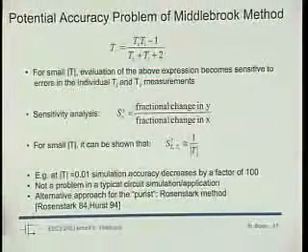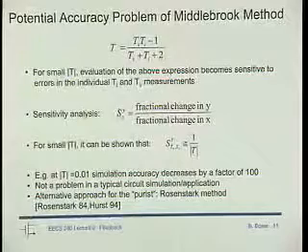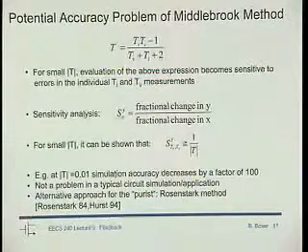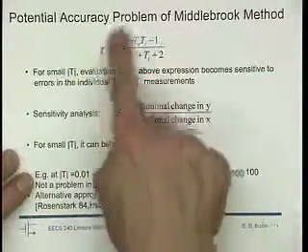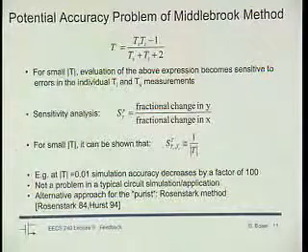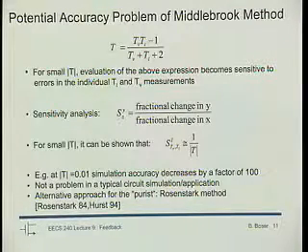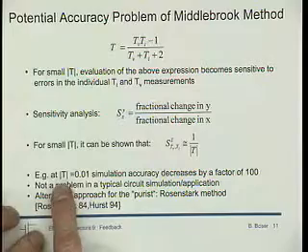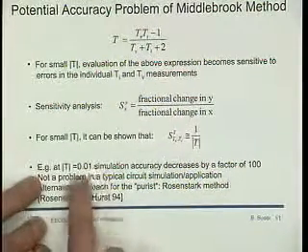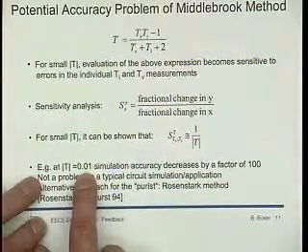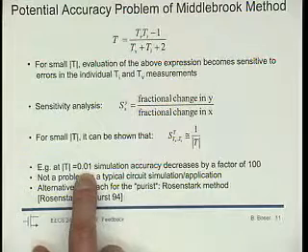then you may come across cases which explain that calculating a loop gain this way is numerically inaccurate, and they are correct in that for very small values of T, the accuracy of the simulation is not very good.